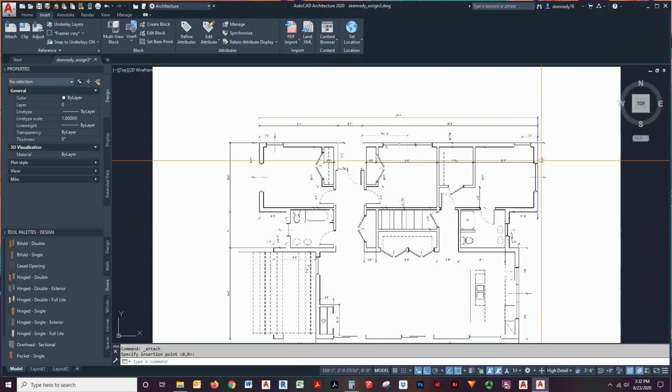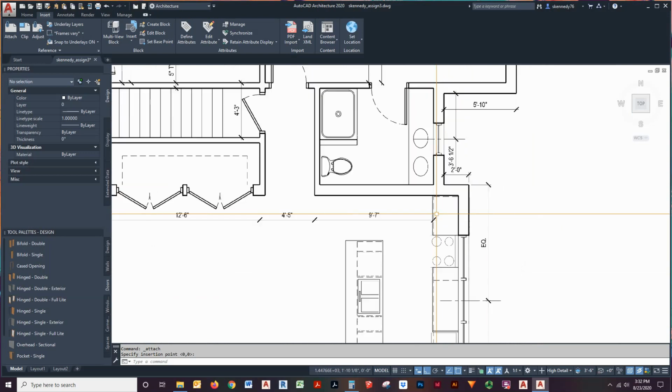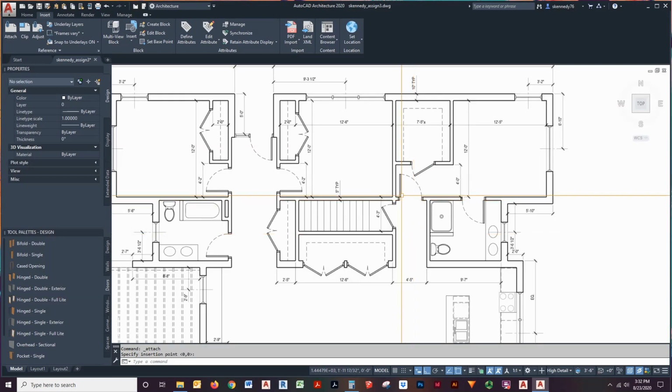Now, luckily, there are dimension strings on this drawing. It gets difficult to scale a drawing if there are no dimensions on it. If you find yourself with one of those drawings, we make some assumptions just to get us somewhere. So if I was looking at a house plan, I would probably go to the kitchen and decide that that's probably a 2-foot countertop. There are certain things we can take as, oh, it's probably this scale. In commercial buildings, for modern buildings, let's say 1970s and up, most doorways will be 6 foot wide, so that is our reference point.